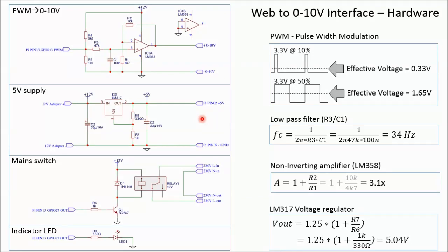I do not use the micro USB input. This worked for me. Also some references on the internet confirmed it is okay for the Raspberry Pi Zero. It seems not recommended for the Pi 3 because there are fuses in between. Anyway, be careful, if you connect this 5 volt wrongly, you can destroy your Raspberry Pi.